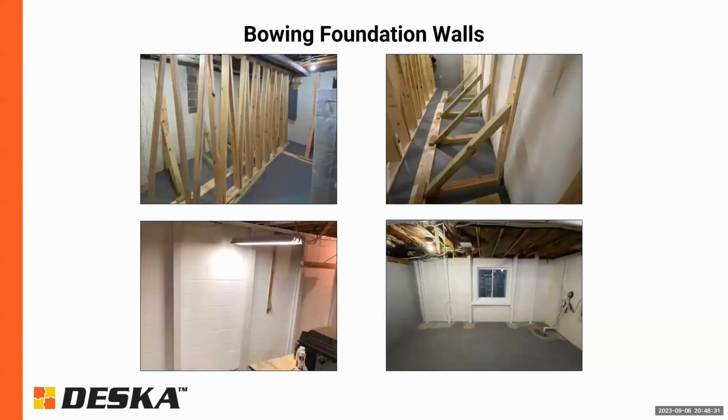However, this is actually the same wall here, and we were able to essentially temporarily brace it and actually push the wall back and install some steel struts. You'll notice we have this vertical bracing here that essentially supports the floor above, since the wall was compromised at that time. And then in the top right here, you'll see we have some lateral bracing as well. And they essentially should be installed at about the same time.